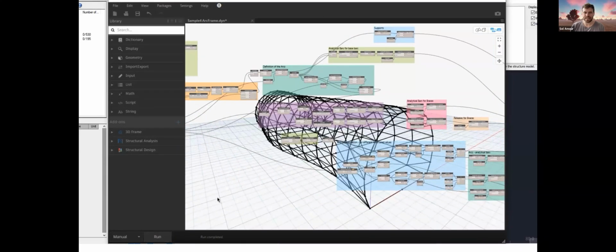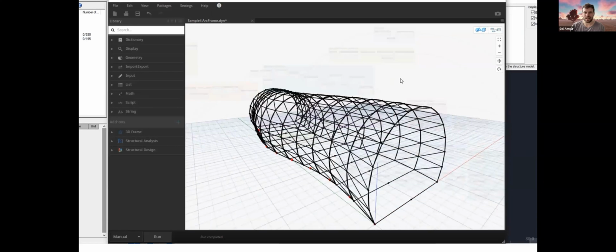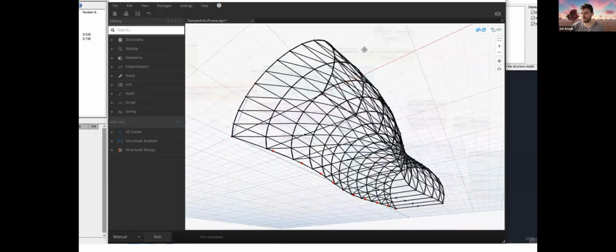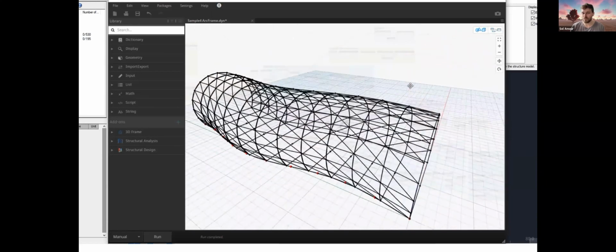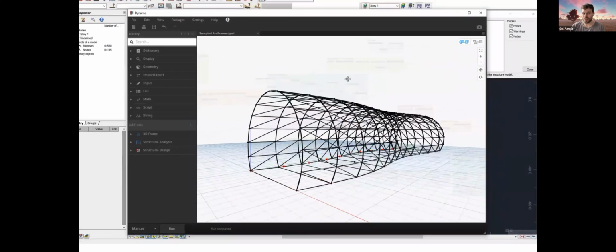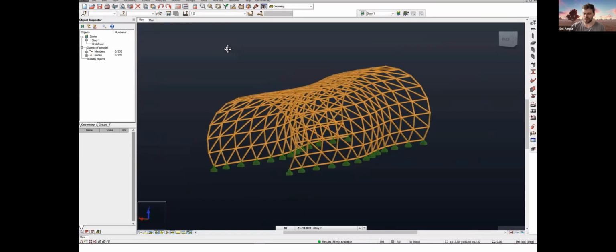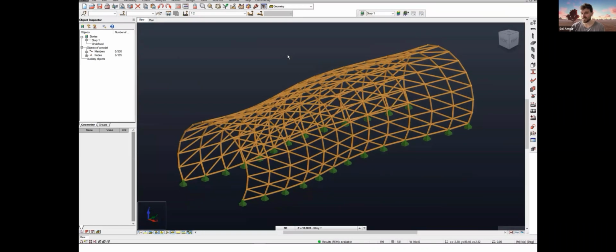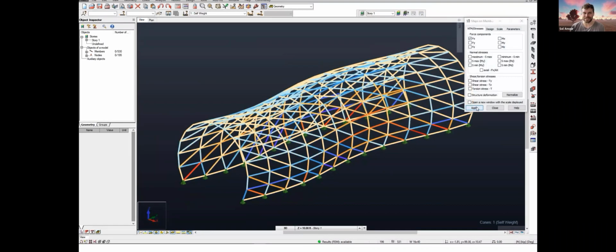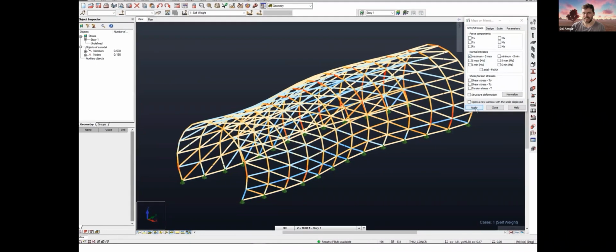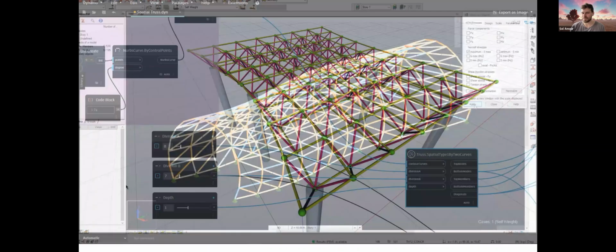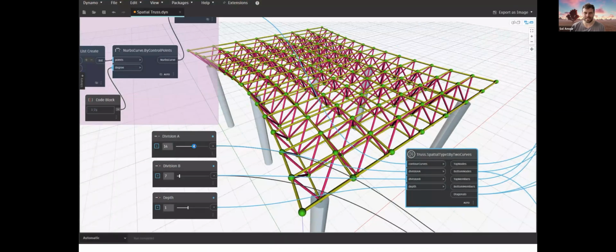So we're going to look at a quick video here that is showcasing this in action inside of Robot and Dynamo. In this case, we're looking at an arc frame sample file. Robot also comes with some really awesome sample files that you can explore. And again, with any of these hosts, you can check out their sample files if you wish to get an understanding of how to generically work with geometry inside of Dynamo itself. So here we're talking about this arc truss and going through mapping and setting some parameters back inside of Robot before bringing it back into Dynamo.